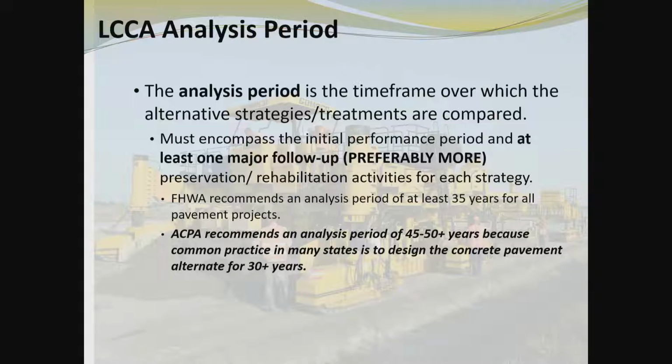In terms of fatigue damage, it probably takes an inch, 2.5 centimeters of thickness. We don't fail pavements by fatigue. We fail pavements because of material degradation. If we can handle that aspect of the pavement, we can make them last a tremendous number of years. But anyway, let's just leave it for the time being and say that it's roughly double the design period should be the analysis period.